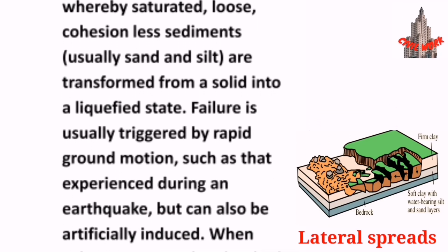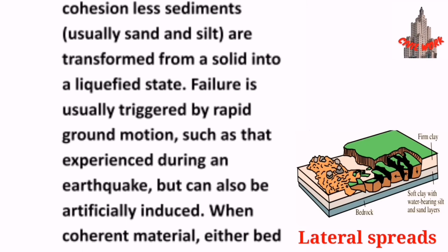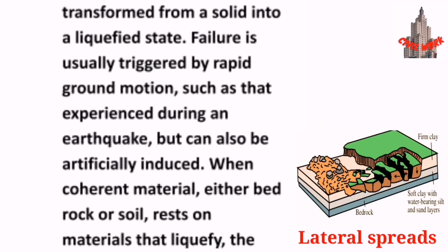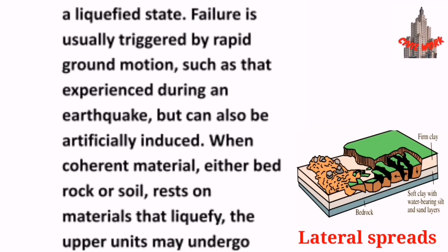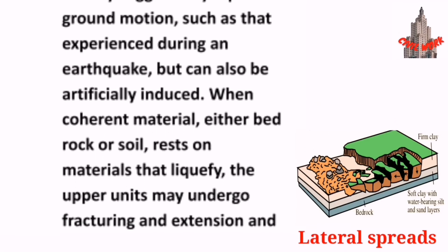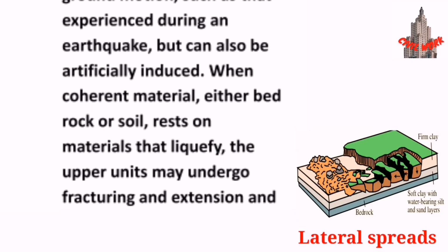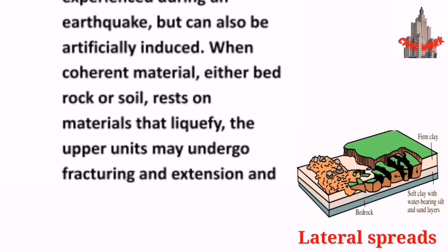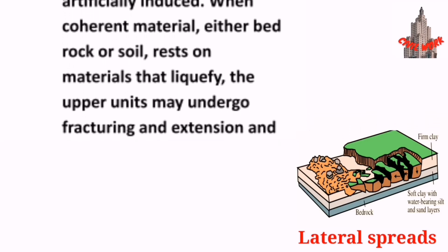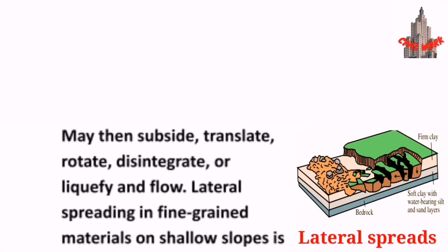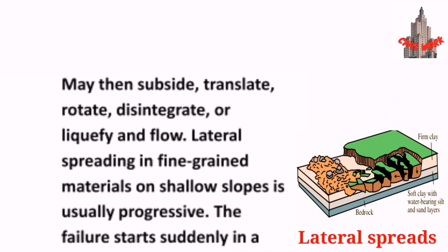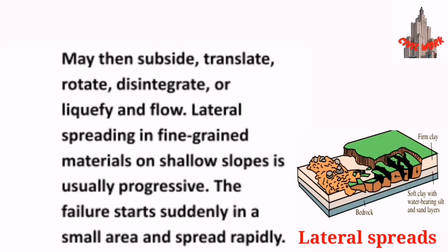Failure is usually triggered by rapid ground motion, such as that experienced during an earthquake, but can also be artificially induced when coherent material, either bedrock or soil, rests on material that liquefies. The upper units may undergo fracturing and extension and may then subside, translate, rotate, disintegrate, or liquefy and flow.